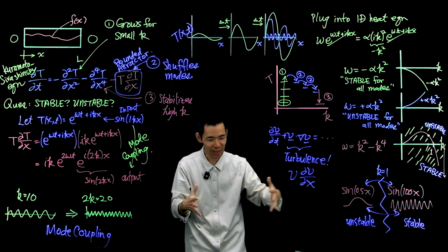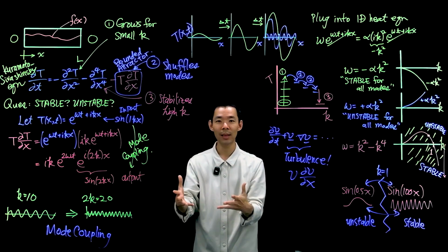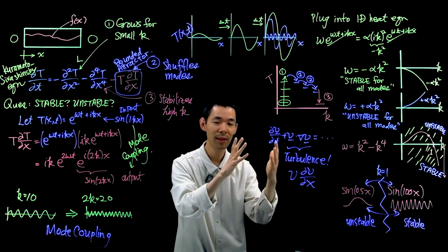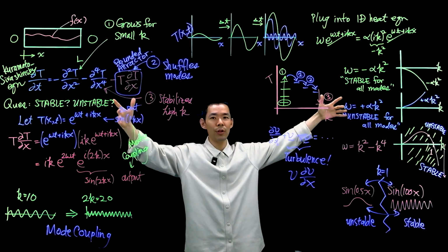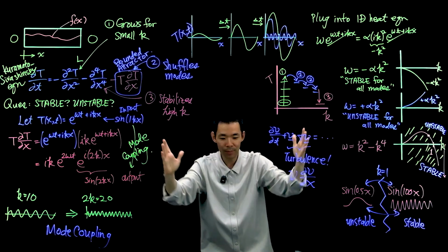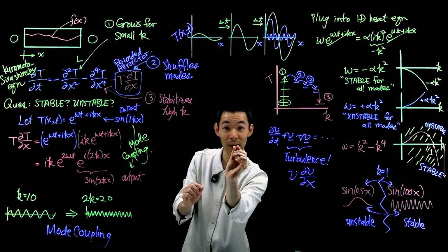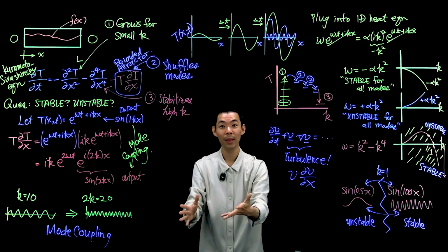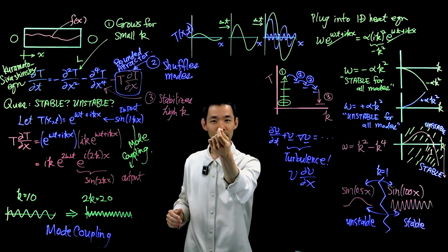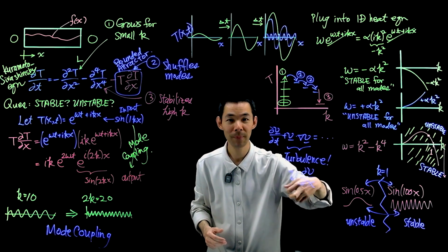People often talk about an energy cascade of small frequencies to high frequencies, or high frequencies to small frequencies. That energy cascade of mode coupling is precisely due to this term. This term is the reason why large hurricanes and tornadoes over a kilometer scale can become smaller and smaller and smaller to a small little eddy happening on a micro scale that eventually dissipates and goes away. The enormous change in scale from kilometers to microns to nanometers, that's possible uniquely because of this term.